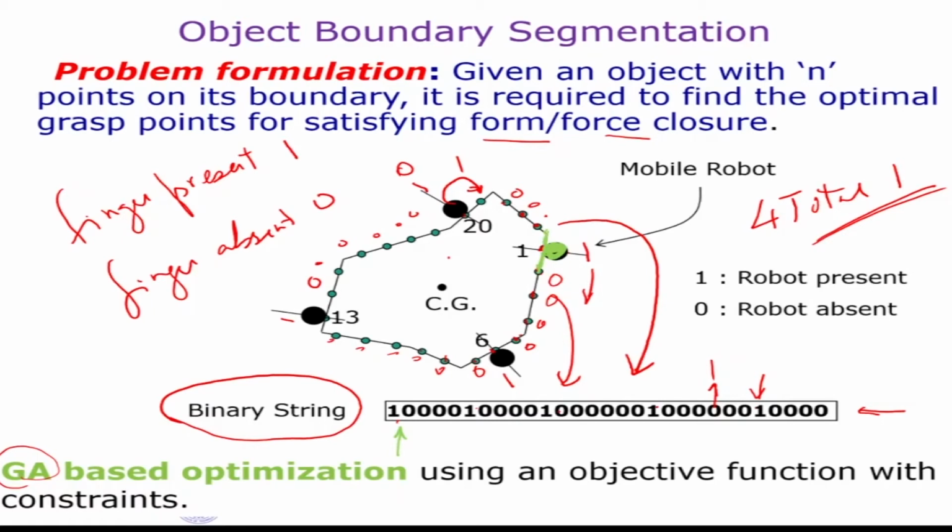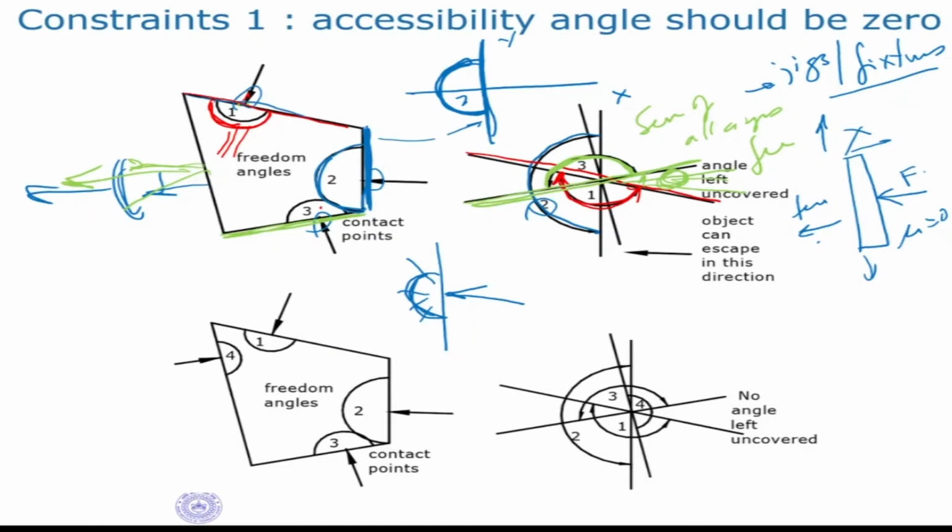So it finds this angle. It can find that angle very easily, and converts it into the total diagram. So it is very easy to find the accessibility angle geometrically. All the program has to do is at every point find the normals. So at this point it finds the normal and then finds this angle.